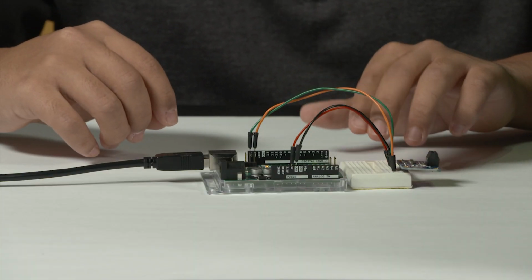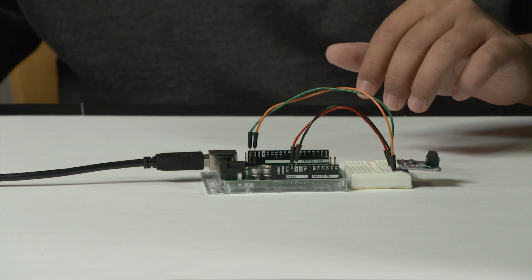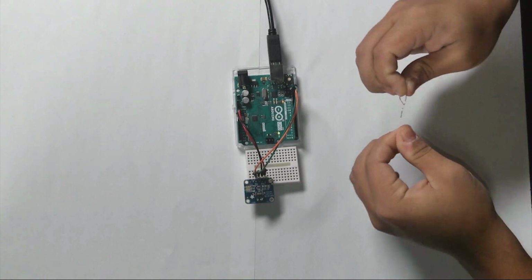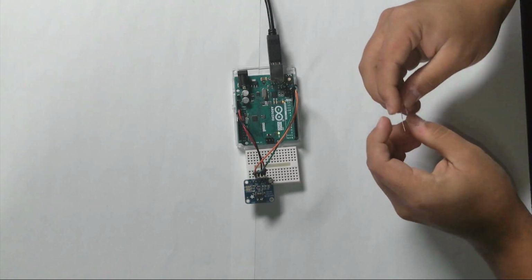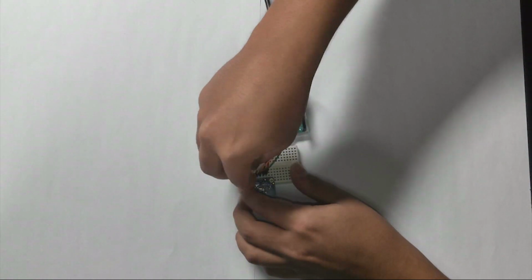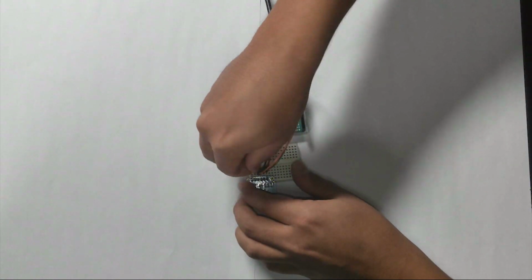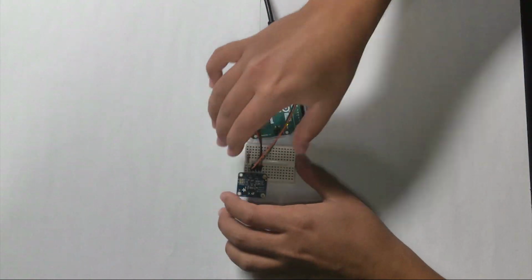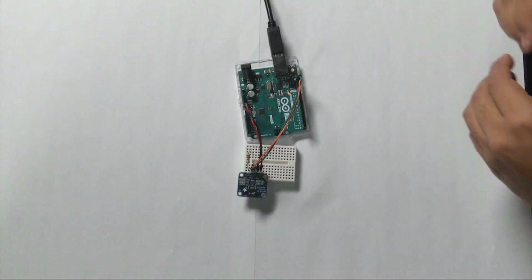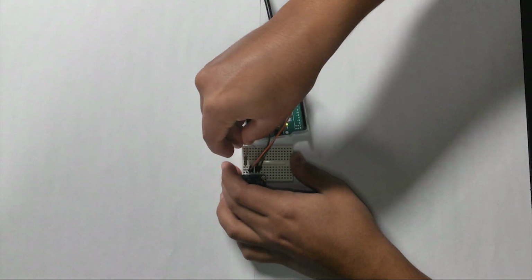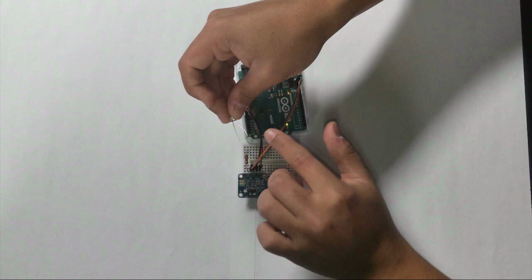The next thing we have to do is connect our resistor to the VIN minus pin of our current sensor. And so we'll do so just like this. So now we have our resistor connected to VIN minus, and we're going to connect the other end of the resistor to an LED. And again, making sure we put it in the right direction.